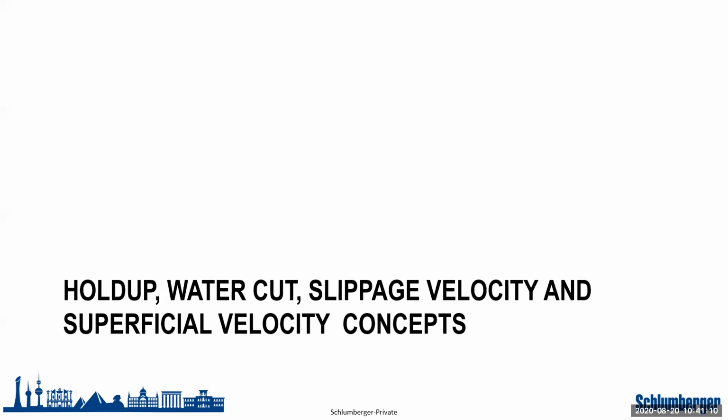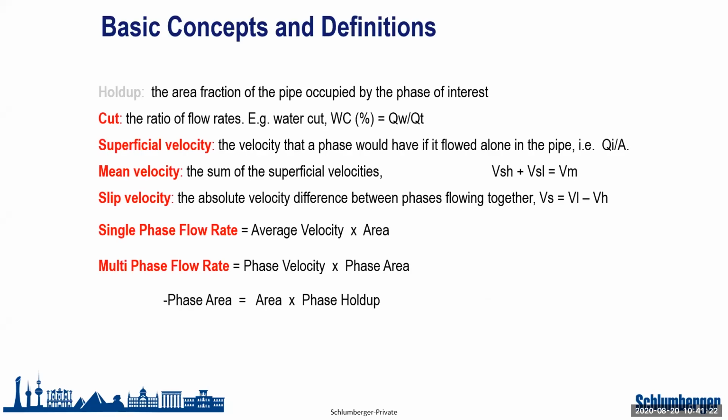Fine. Now, to enter into a well that is going to be producing multi-phase, we need to see some basic concepts. Okay? So, number one, hold-up. What is the hold-up? Hold-up is basically the area fraction of the pipe that will be occupied by a phase of interest at any particular point in time.